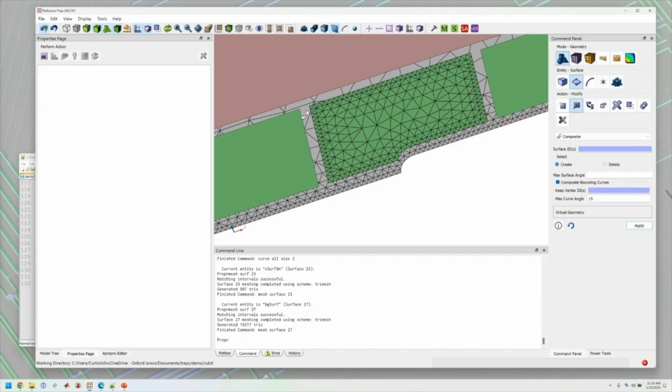It'll be stuck trying to solve a line charge in these huge triangles, and it'll fail. The evidence of that will be that it takes a long time to converge, and also it will converge to a bad answer. You will have a bad simulation result.